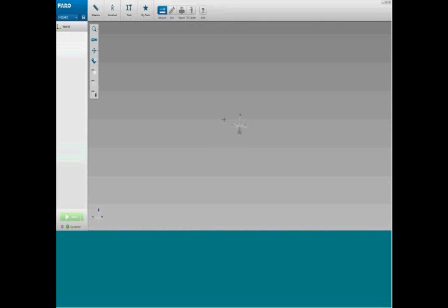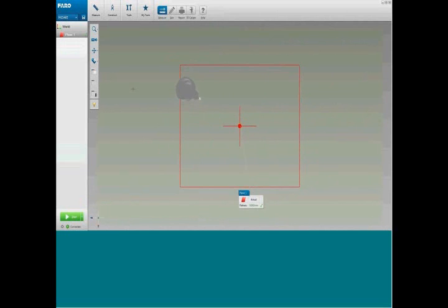Okay, I could measure the features now, as before, from the top. But this is an ideal opportunity to demonstrate the auto recognition feature to you. So simply start probing the feature. And the auto recognize feature is activated. And it will offer me the best fit feature depending on the position and number of points I take. To accept, I simply compensate. And now the 3D viewer aligns to that plane. Should the auto feature get it wrong, it will offer you other features within the window, which I'll show you in a moment.